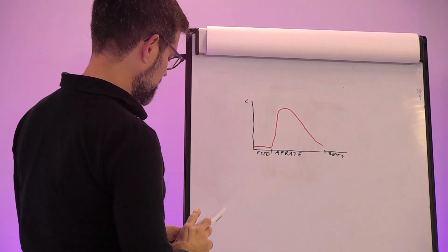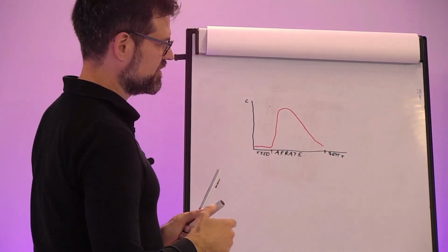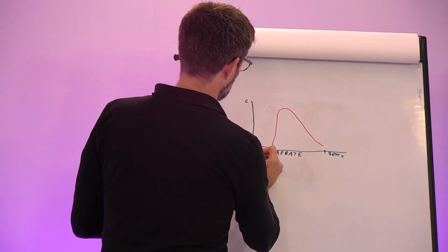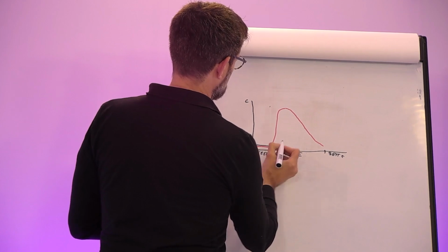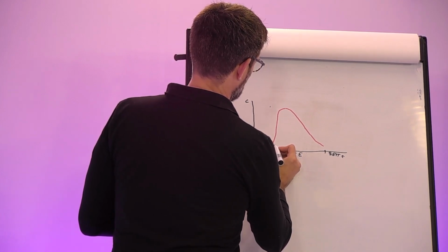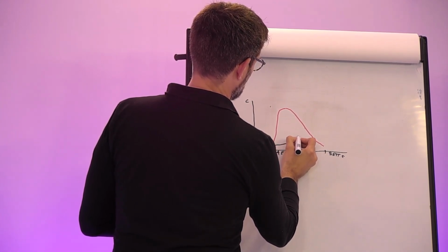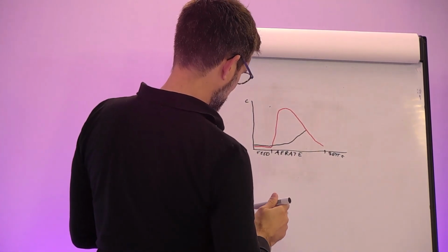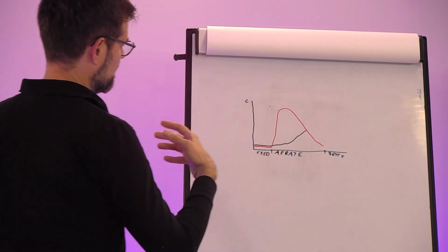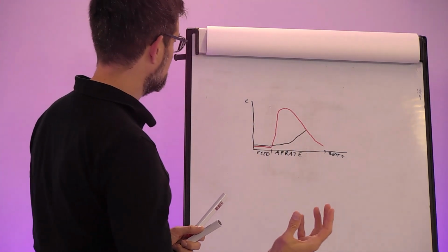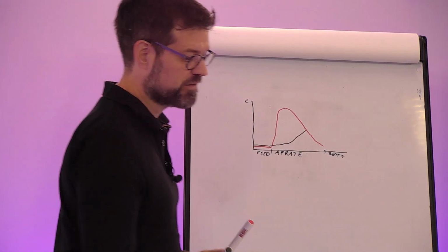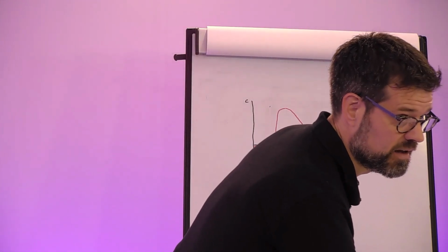What you will also see during that aeration is that we start building up our nitrates. That's also low during the feeding phase, and then we start producing nitrates because we are converting ammonia to nitrate. But what will actually happen is that we see less nitrate back than what we would convert from ammonia because of our simultaneous nitrification, denitrification.